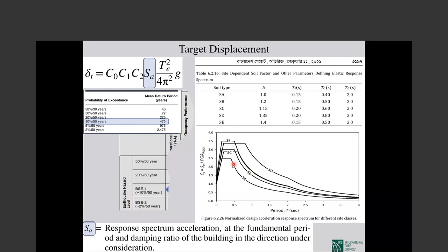but sometimes it's worth to do site-specific, because for this site-specific, maybe you get a smaller value. It's a specific site, and it becomes even your retrofitting becomes even cheaper. So many times it's better to do site-specific responses. Anyhow, one very important aspect is we should have this curve. For example, one of them based on the soil, this curve for the given level of earthquake. So we have this now.